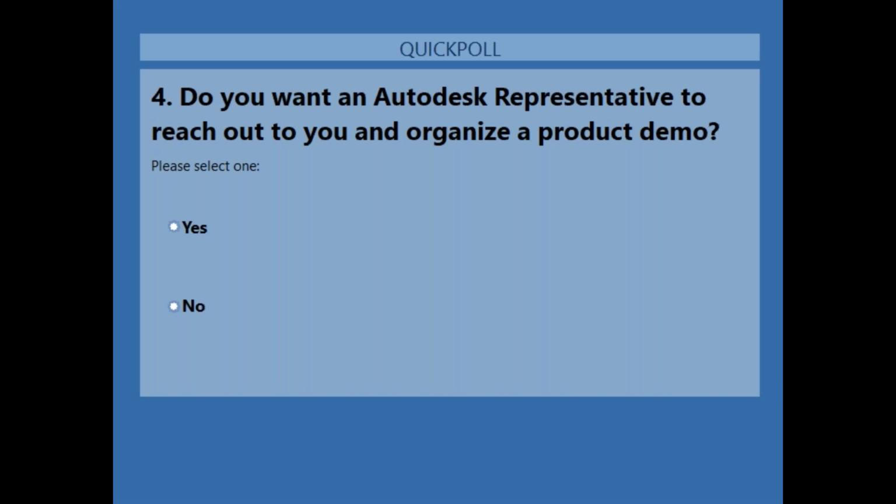You can export your schedule to Excel, make some changes in Excel and bring it back into Revit, including element properties, like type properties that can be edited. There are certain apps for that in our App Store, or you can use Autodesk DB Link. You can use either Excel or Microsoft Access to do that. I hope that is answered.